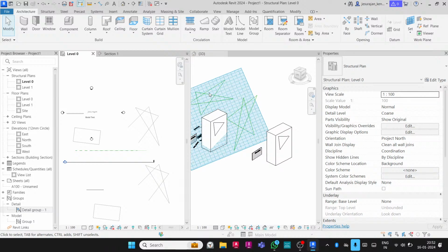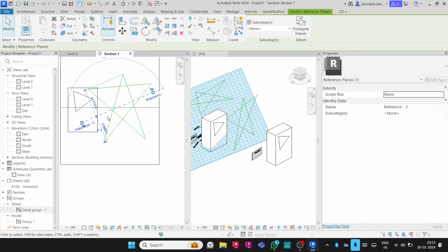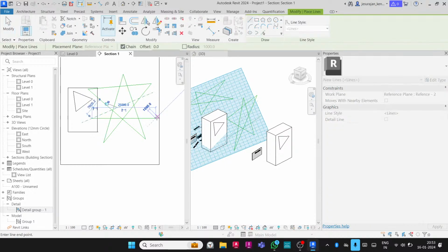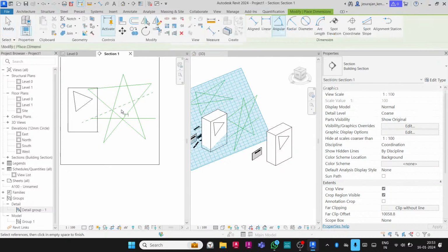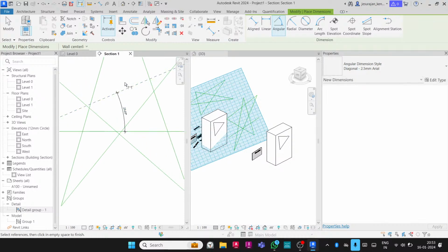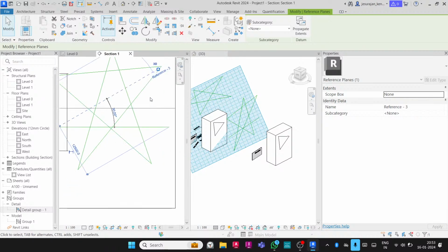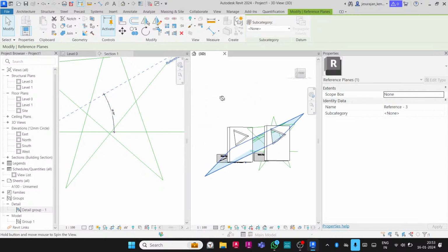How to set a specific angle? Yes. When you are drawing it in the section, then you have to set it for the right degree. So you need a reference. So let's draw a horizontal line and then measure angle. Select the line, change the angle to 30 degree. So now this is exactly at 30 degree.